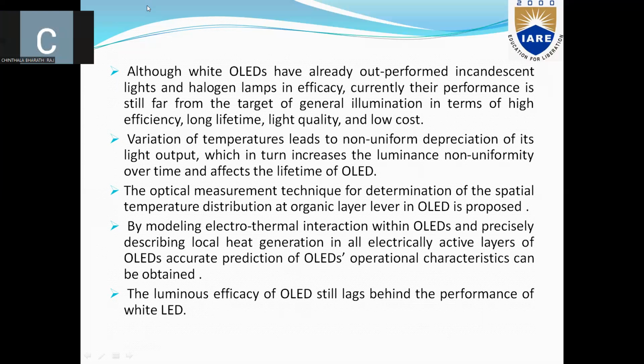Variation of temperature leads to non-uniform depreciation of its light output, which in turn increases the luminance non-uniformity over time and reduces the lifetime of OLED. An optical measurement technique for determination of the spectral temperature distribution at organic layer level in OLED is proposed.